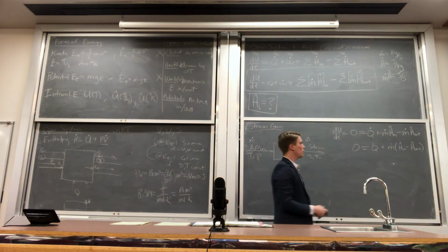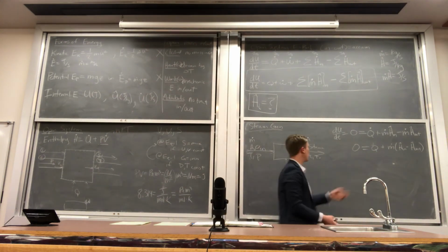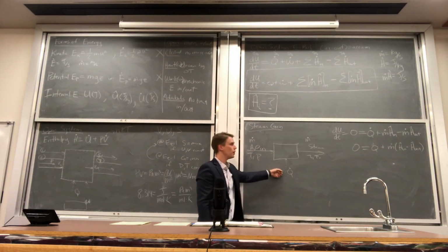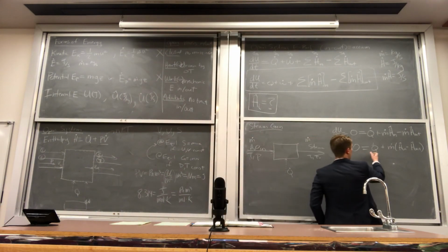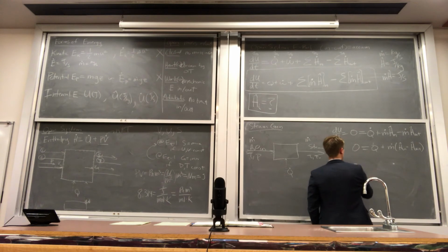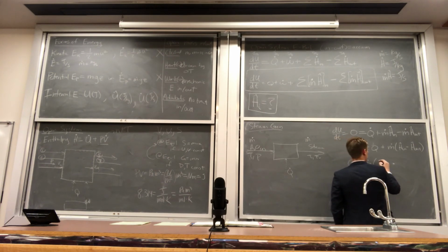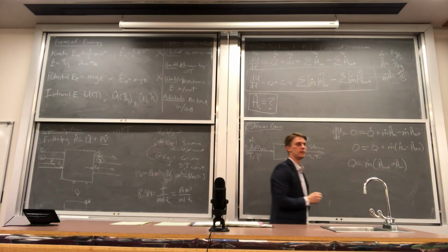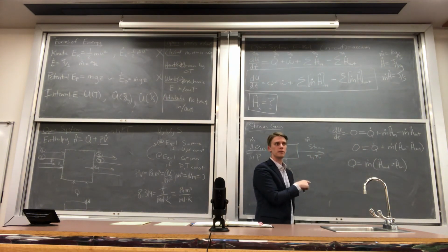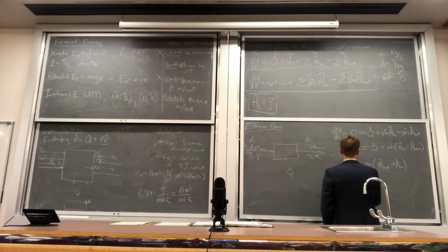Right? And then what we care about is Q, right? We know how much steam we need to generate for this process. We just need to figure out how much energy it is going to cost us to make the steam. So we'll solve for Q by moving this to the other side of the equation. We get Q dot is equal to m dot, but in this case, it's h out minus h in. And how do we typically write this? Bingo, delta H. Q dot is equal to m dot delta H hat.